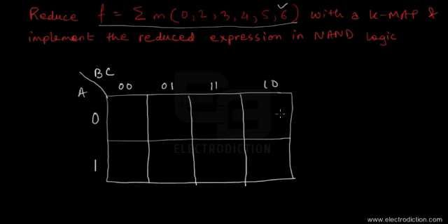Okay. So now what remains is the number of the cells. So let's just put it over there. So we got the cell number 0, 1, and then 2. Sorry, there. This one, 2, would be here, and this will be 3. Okay, and then we got 4, 5, and then 6 and 7. So kindly don't make the mistake that I was just making a little while ago. You should always make the 3-variable Karnaugh map something in this way.